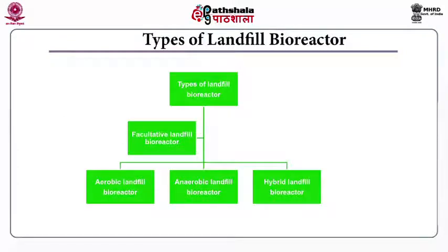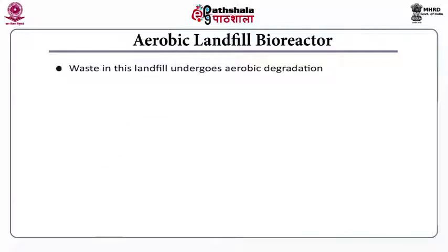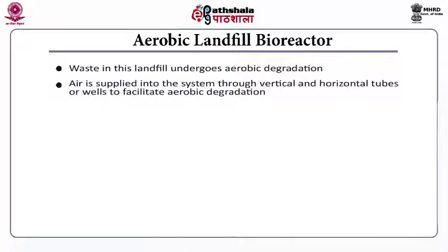Landfill bioreactors are of three types. They are classified based on the working mechanism as aerobic, anaerobic and hybrid landfill bioreactors. In an aerobic landfill bioreactor, waste generally undergoes aerobic degradation. Air is supplied into the system through vertical and horizontal tubes or wells to facilitate aerobic degradation.